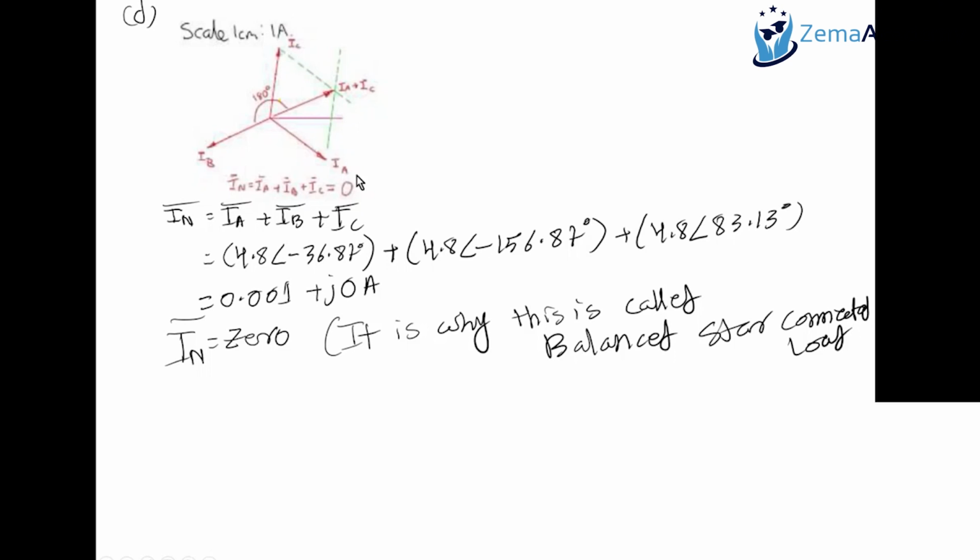By drawing the parallelogram means two imaginary lines at the point of intersection. This will be your IA plus IC line. Now it can be seen the length of the line and the angle of the line is opposite to IB. And mathematically, if you add two opposite lines on a phasor diagram with the same magnitude and same angle, it will give you the 0 point. It's like two lines at the same angle will subtract to each other if you add them.